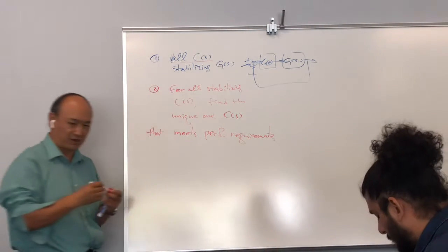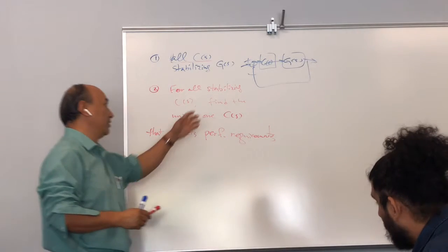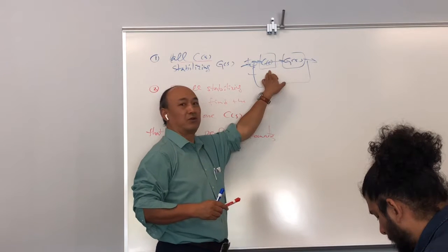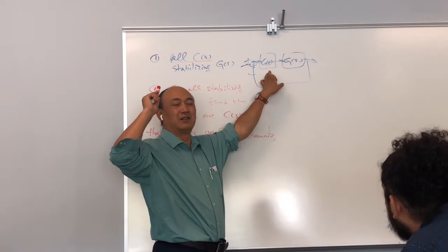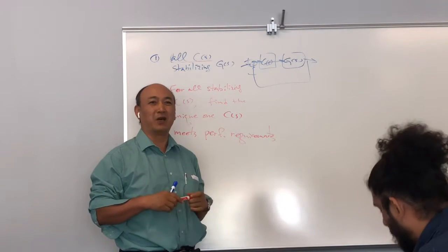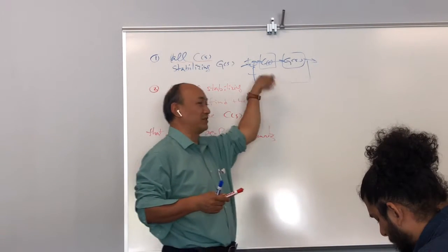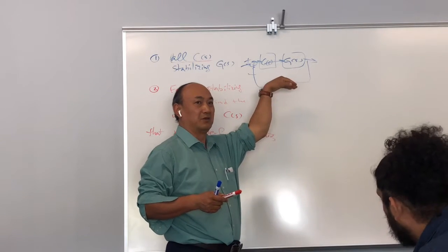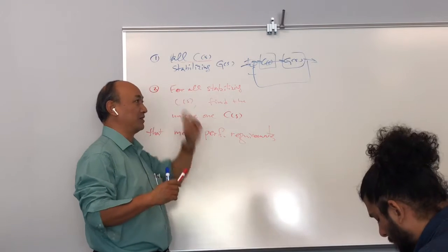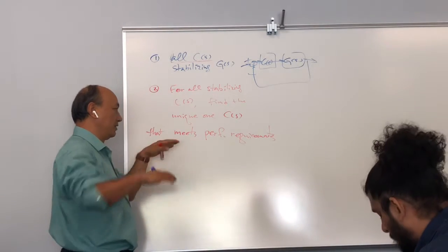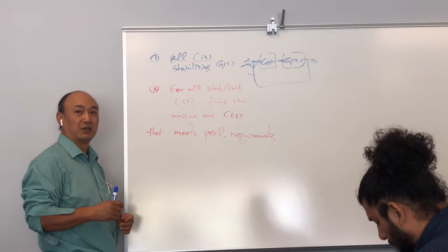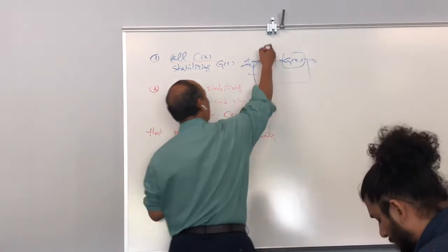Okay, I hope this is very clear. So you have a plant you want to control, and you find only one controller. You choose that one, and why this one, not that one? Both of them can make the system stable. It's because I have a performance index, and that one has the smallest, the minimum. Okay, that makes sense, so that it can be unique.